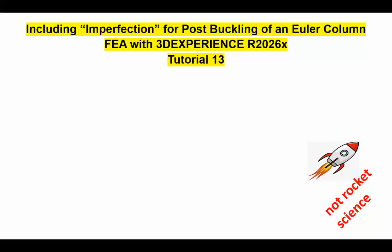You had to go to, because the FEA software is Abaqus, you had to go and create an Abaqus input file after the linear buckling analysis. Not input file, but it's called, I think, a FIL file. And then once you put some commands in there, you have to save it and then read it into 3D experience, and then start from that point on. That's how you did the imperfection in Abaqus.